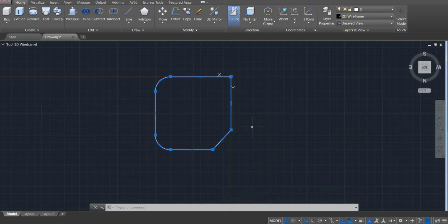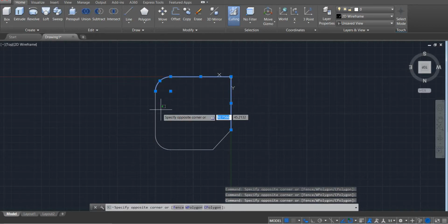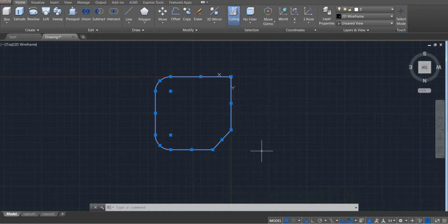If you choose the loop which is already joined, you can extrude it. You just type extrude and press enter, and you're gonna end up with these lines separate one more time. Then you can join them back again and extrude, it's up to you. So the extrude command will extrude the joined object into multiple objects again.